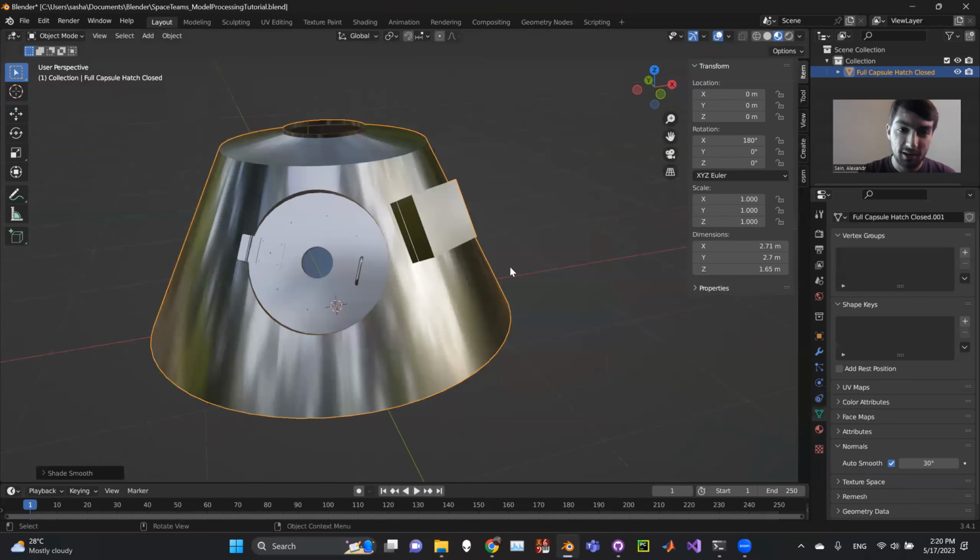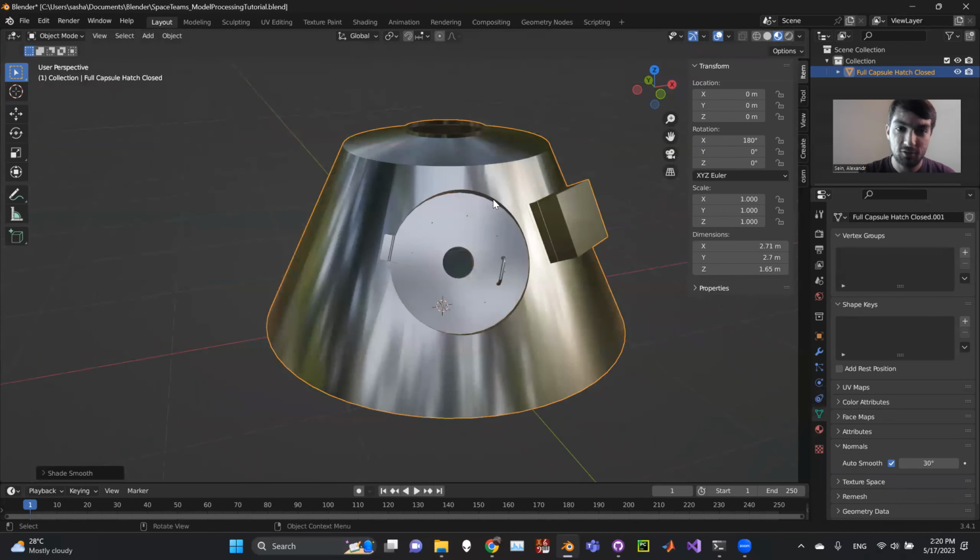So now we can try to kind of improve on this material, right? The actual material that you'll get in the file has a texture on it, but for some reason it's not showing up. And that reason is that the model is not unwrapped. That means all of the geometry isn't assigned to a 2D plane that the material can then map to.